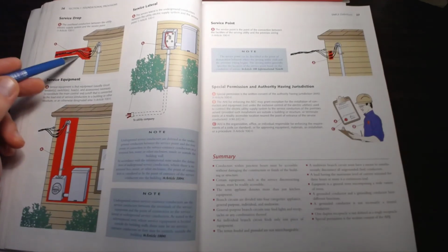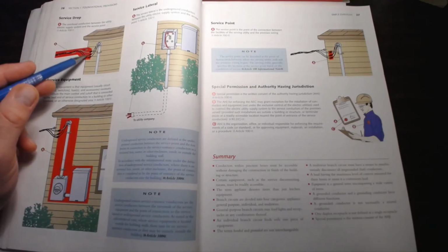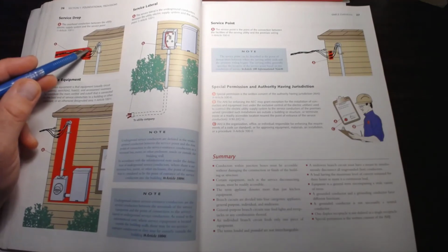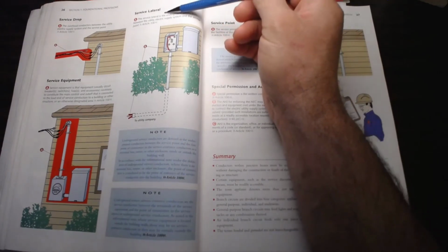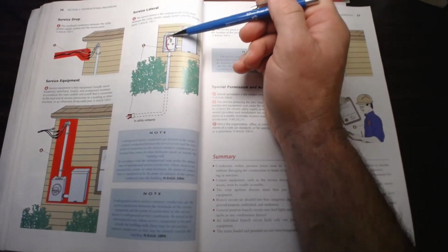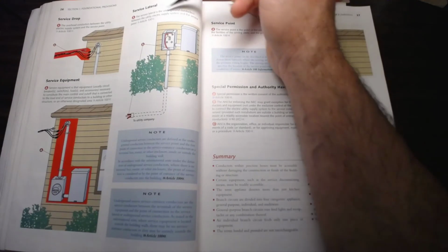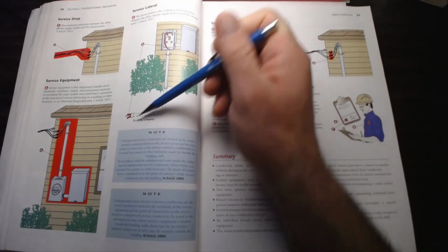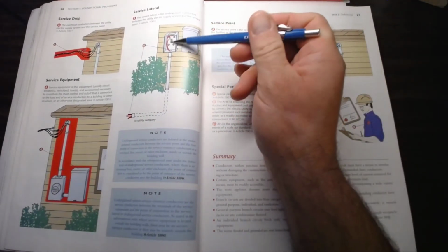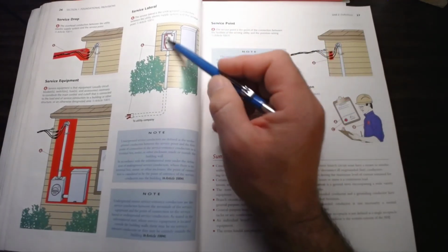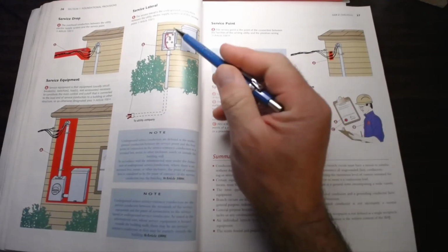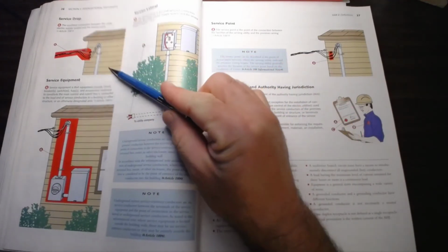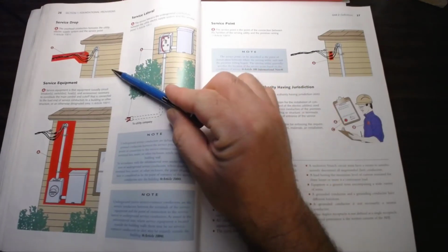There's the two types of wire. So triplex has 3 wires, quad has 4, and it stops at the termination point where the utility connects to the service wires. The service lateral is going to be from the connection underground, so it comes underground and goes up into the panel where the meter can or meter panel is, and that is going to be the service lateral. So remember, service lateral is underground, service drop is overhead. Lateral underground, drop overhead.